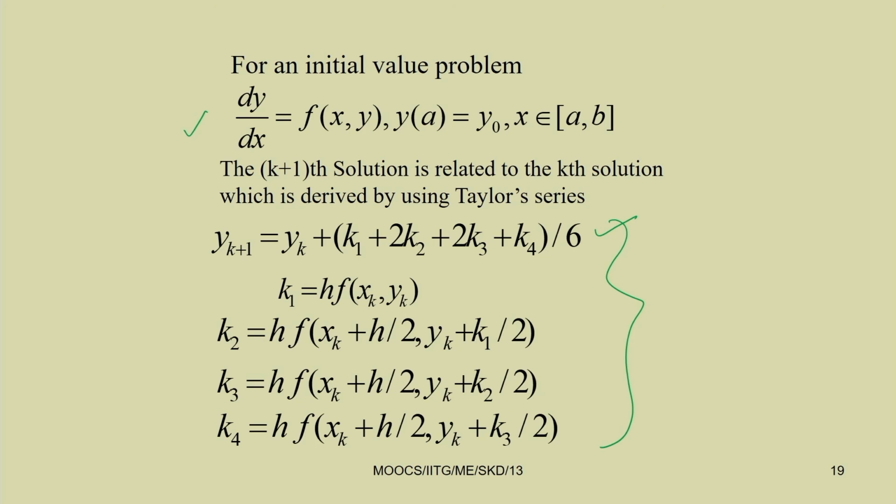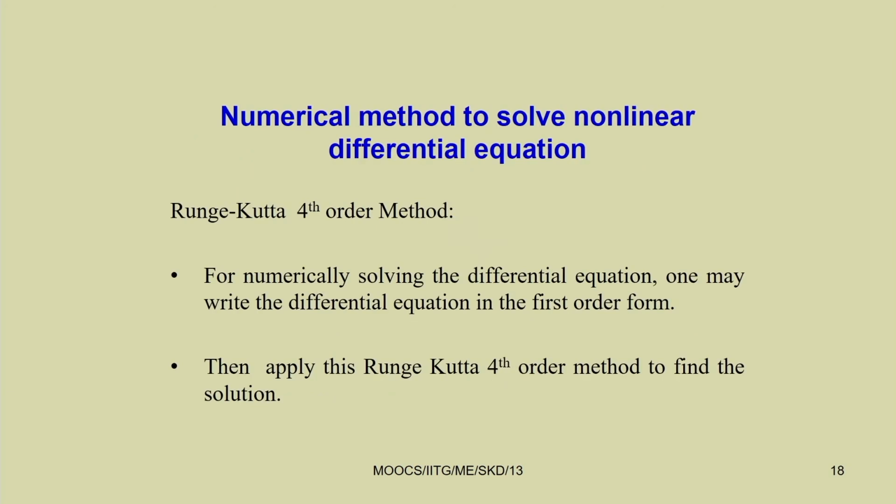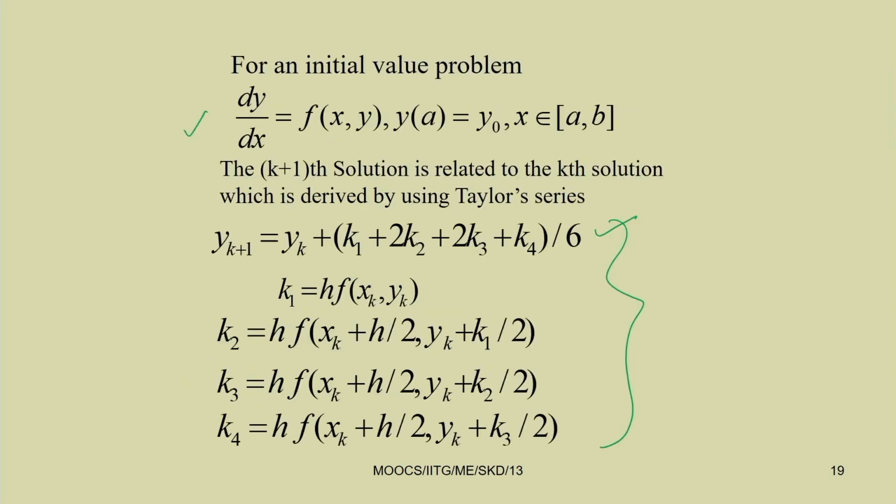You can write your own code by using these equations, or you can use different functions available in different software, for example, in MATLAB. In MATLAB you have ODE45, ODE23, ODE15. Different methods are there for different types of equations. Sometimes the equation may be stiff, sometimes the equations may be of different types. Depending on your equations, you can use different functions.